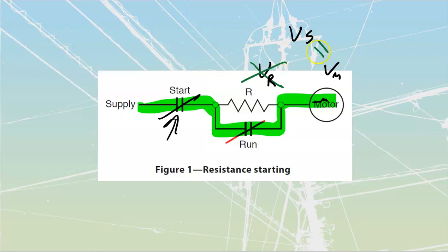What we'll do is select this value of resistance to limit my motor voltage, so that it can limit my current. Now, we do want to limit it, but we don't want to take it down too low. We saw what happened when we squared 50% voltage in the previous one: we were only at 25% of our startup torque. So usually we're going to want to go higher than that, because it's a squared value.